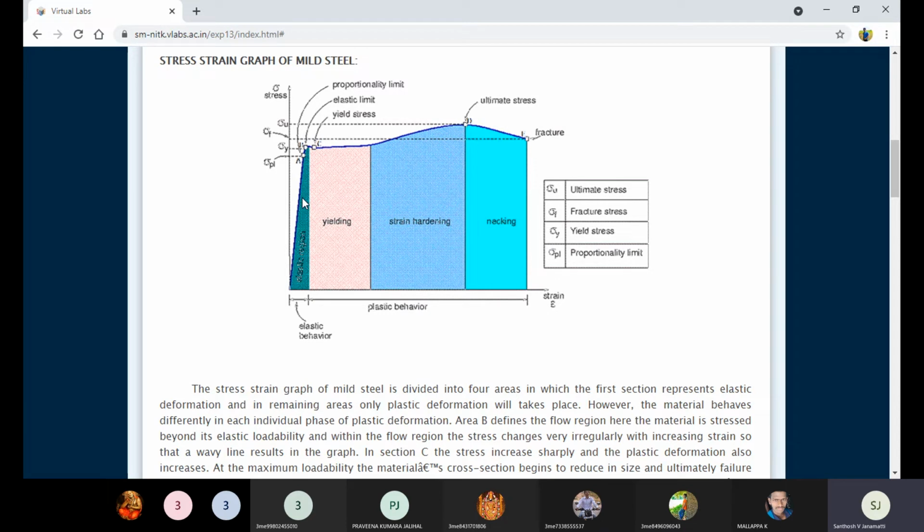That's enough for the engineers to predict their service life. There is no need to go up to the ultimate. Once they have the stiffness value as well as the yield value, that's enough for the engineering applications of that particular material. Technical persons and very experienced engineers can predict the service life, hence they will not conduct further tests, because yield point and stiffness are very important for engineering materials, right?